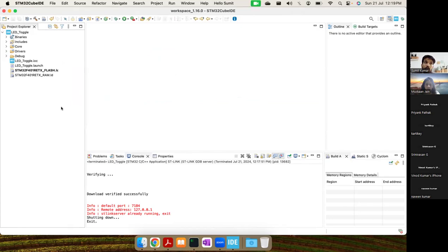For different peripherals, for example in the case of UART, you need two pins, TX and RX. Any GPIO pin can take input from the outside, or can drive output on it, or it can be in an alternate function mode.